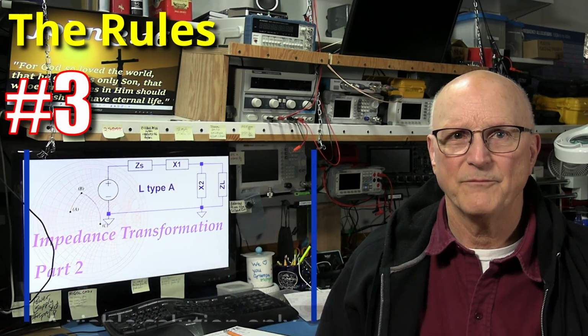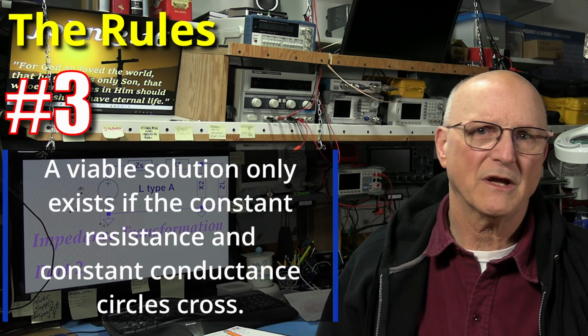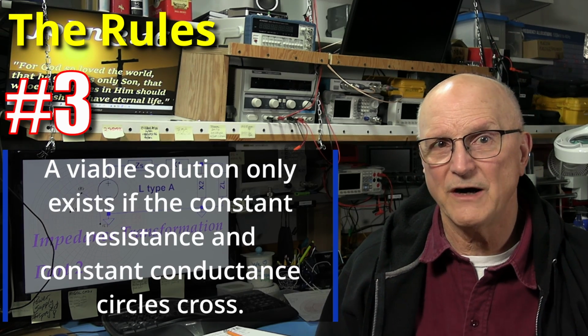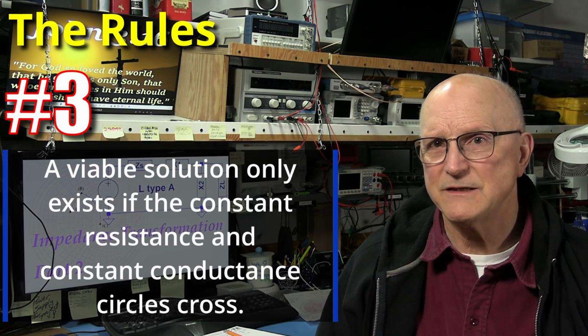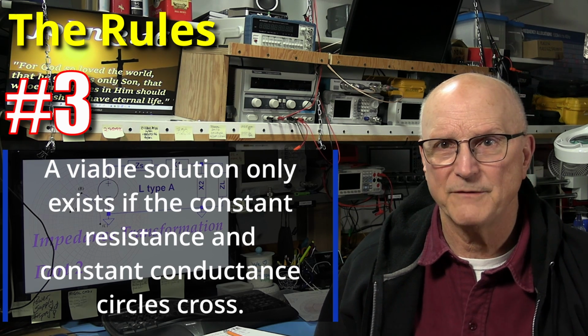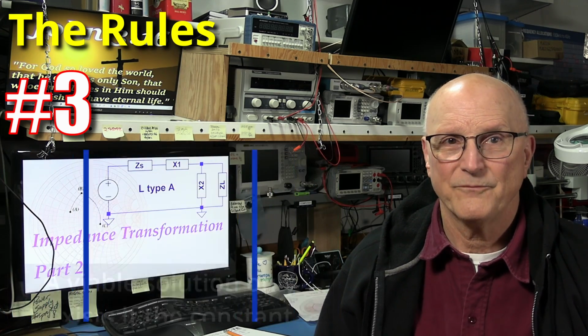Rule number 3. A viable solution only exists if the constant resistance and constant conductance circles cross on the Smith chart. We are traveling from one impedance to the other using the constant resistance and constant conductance circles as our path. If they don't touch, then we can't get there from here.